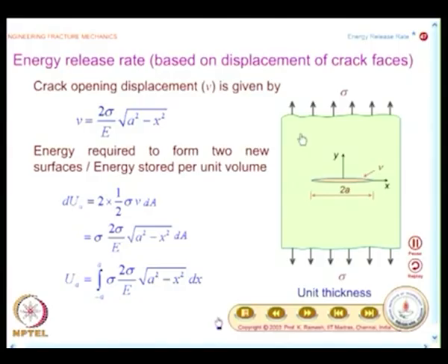Now, after learning all of those developments, and also the current developments, what you can really look at is that, whatever the result I have used, I can replace this diagram by a horizontal loading also, and then apply this. The situation is the same whether it is uniaxial loading or biaxial loading. We have used the biaxial loading result. Only for a biaxial loading result do we know the definition of K as sigma root pi a. It is not strictly a definition for uniaxial. So from that point of view, you have not made any mistake.